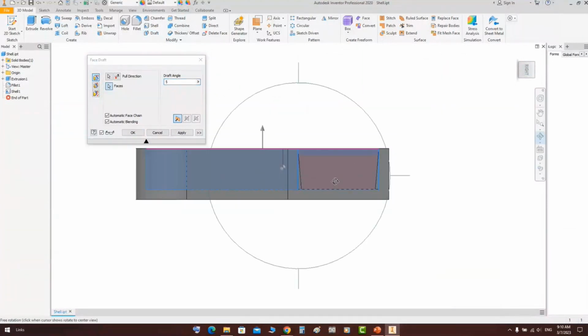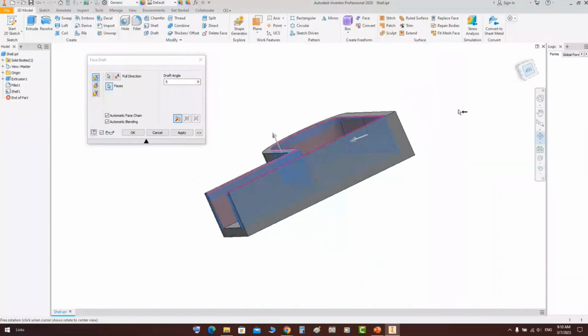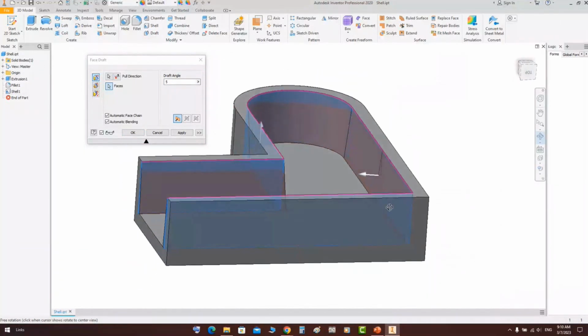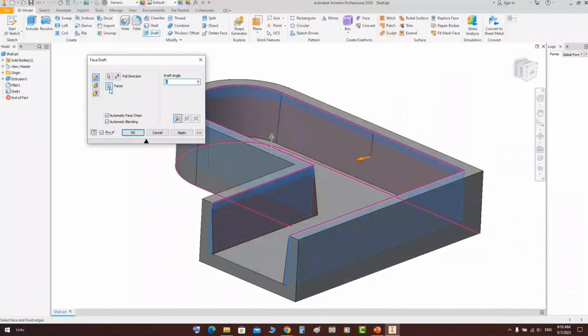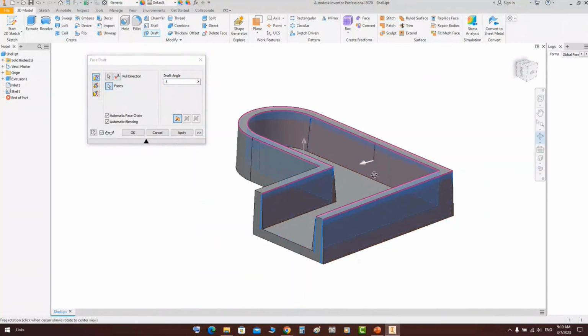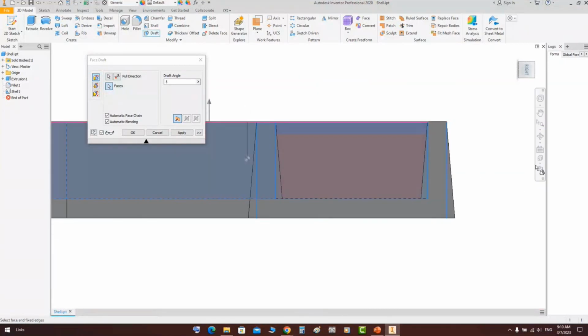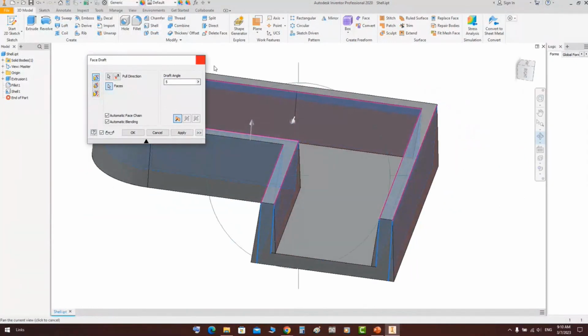You can make this surface drafted like that, so you can easily move it out from the sand that way, and you can select other faces like that. So you select faces like that, and you can make a draft for those faces during creation.